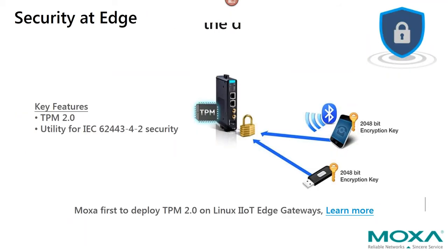This brings us to the third common question, security. First, let me say security is an ongoing topic. As an example, we find that many customers' OT networks today can be made more secure by ensuring passwords are changed or updated, or that the right VPN and firewalls are set up. Although this is the responsibility of the operator, Moxa is working to offer tools that can survey a customer's network and offer guidance based on a green, yellow, red color code that meets IEC 62443 security levels.